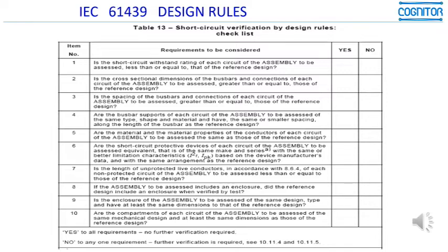If the answer is yes, this means in a first approach that when the equipment is subjected to a short circuit, the electrodynamic forces which will occur in it will be lower than the ones that occurred in the tested equipment, because the larger the distance between phases, the lower the forces.